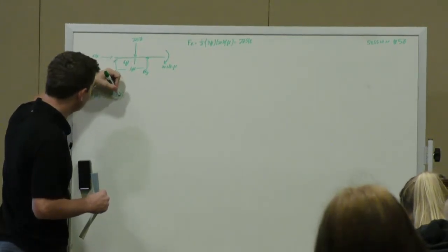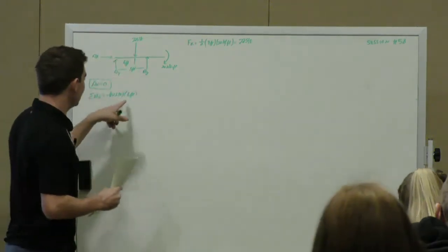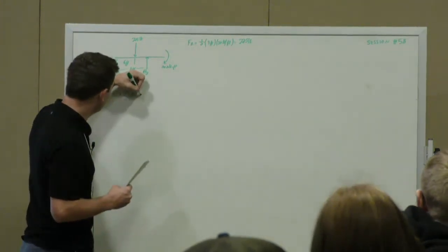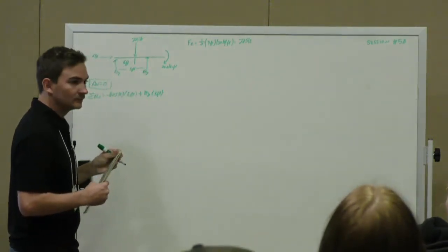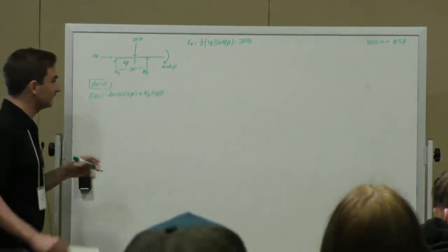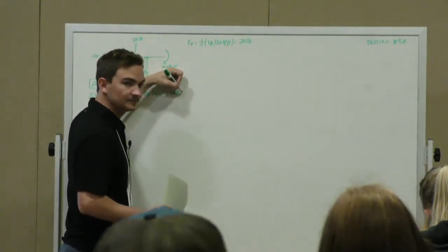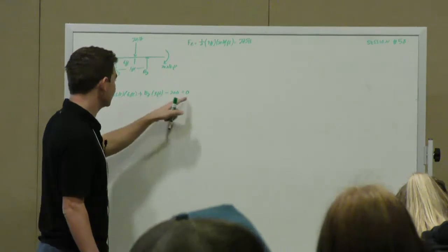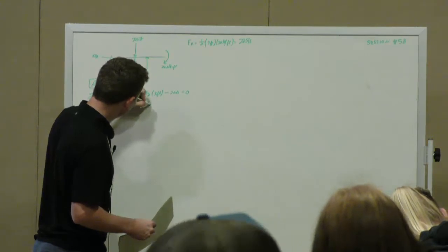Very good. So does everyone see that? Using the right-hand rule, this 225 pounds causes a negative moment, and that's acting 6 feet away. So what about anything else? BY. Very good. So what does everyone think? Does this couple moment cause a positive or negative moment? Negative. Yep. So it's clockwise, so it causes a negative moment. And what is this all equal to? 0. Very good. So just adding the 200 and the 225 times 6 over and dividing by 9, we get BY is equal to 172.2 pounds.